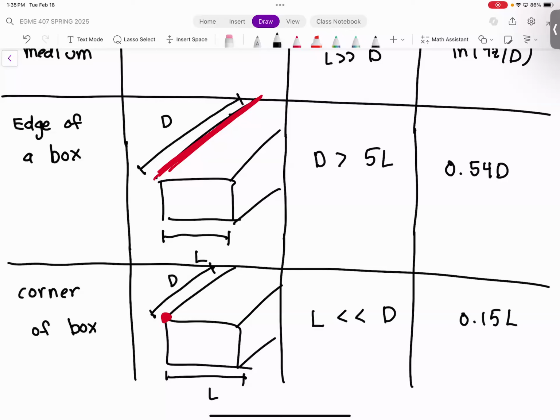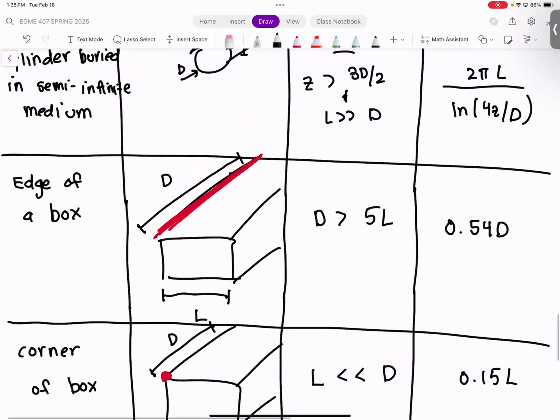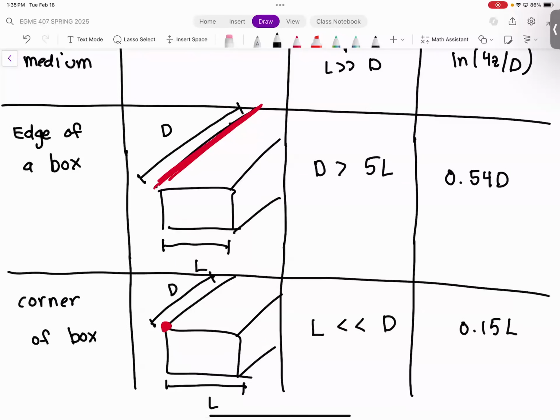Okay. So those are just a few examples of shape factors, but again, if you look at table 4.1, there's a lot more in there. So when you have a 2D heat transfer situation, first thing I would check is to see if table 4.1 has a shape factor for your specific situation. If it's something that occurs very commonly, it's likely going to be in table 4.1. If not, then you would have to solve the full heat equation. All right. Questions on this before we do one more example of this? Okay. All right. So let's do one more example.